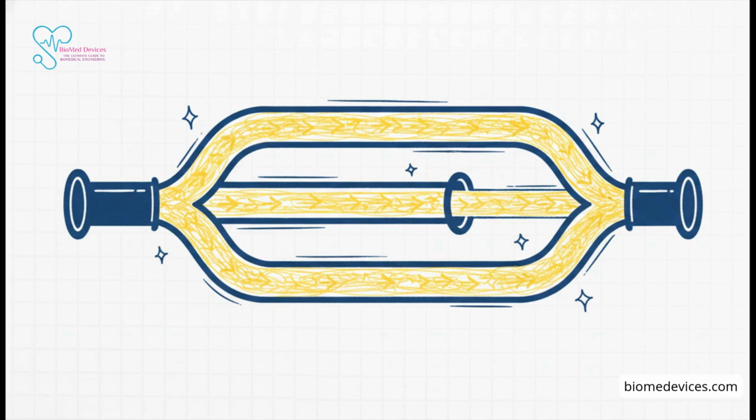Let's solve a really simple conceptual example. If you have two 10-ohm resistors in parallel, intuitively, having two identical paths makes it exactly twice as easy for current to flow. Therefore, your total resistance drops right in half, to just 5 ohms. See? No complex calculator needed, just pure physical intuition.